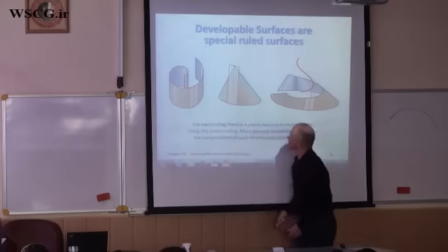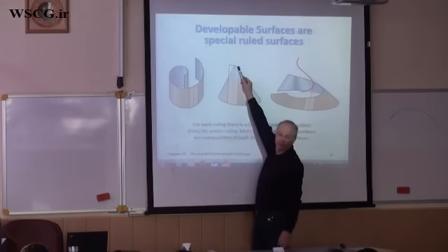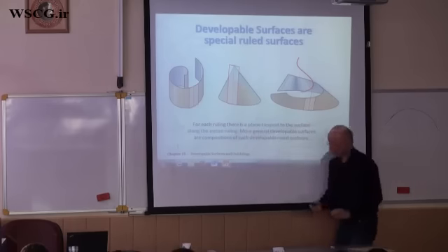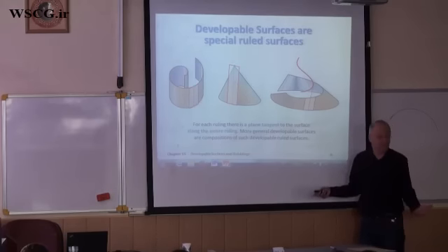The second case, all planes which you move pass through a fixed point. This means that the envelope surface is a general cone. It is formed by a family of straight lines, all of which pass through a fixed point, the vertex of the cone.